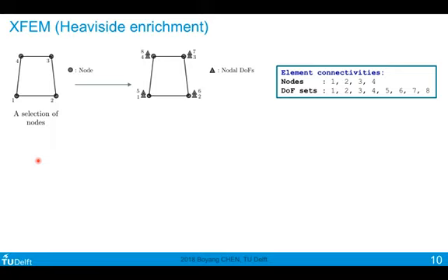Recently, a very popular approach is to use the so-called extended finite element method. In the extended finite element method, the elements are enriched with additional degrees of freedom and additional interpolation functions. For instance, an element in the finite element method is composed of a selection of nodes. You have an element defined as a nodal connectivity matrix.